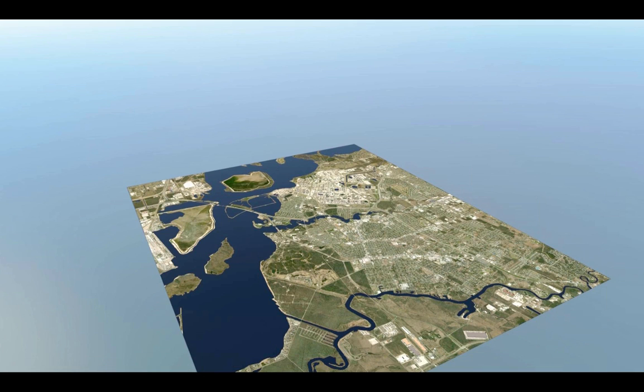What we're able to do in InfoWorks is to be able to quickly and easily create a conceptual model. So we're able to aggregate all sorts of information, from digital elevation models and topos to aerial imagery from, for example, Google or Bing Maps, from USGS, for example. Different types of GIS data, shape files, line work, also 3D models, and point cloud data.